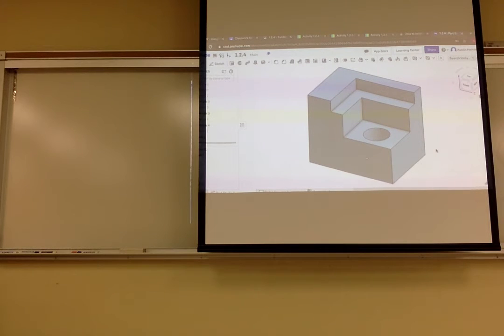Now what you need to do is cut. It's an extrude, but not adding things, it's removing things. You're going to see there's this big rectangle that gets cut like half an inch. If I draw that rectangle and extrude remove it by a certain distance, that'll cut out what I want. So go to sketch on the top, and you're going to draw a rectangle.